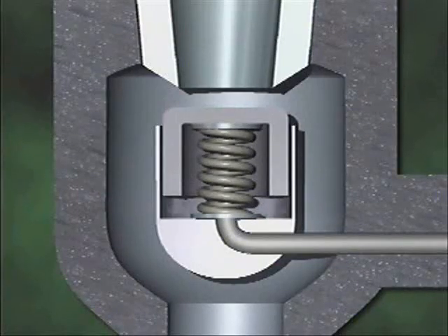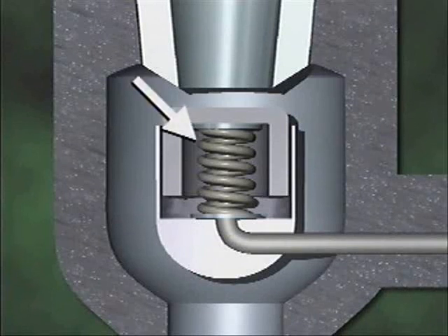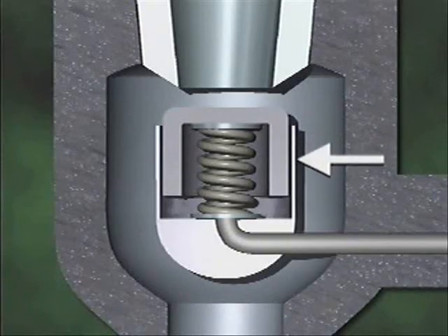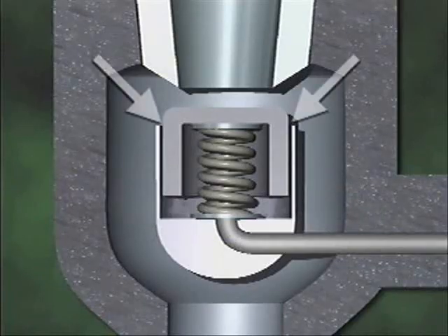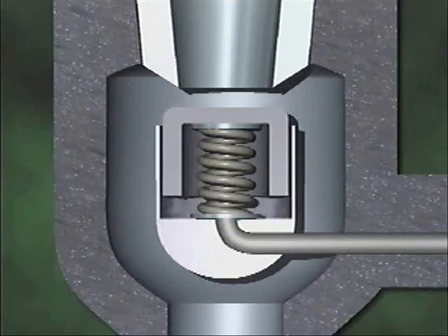The disc opens downward, allowing the steam to escape through the outlet at the upper part of the valve body. Also, in this example, the spring is placed below the disc. The valve also has a disc guide, which is a sleeve that aligns the disc with the seat. A small opening between the disc guide and the disc allows system fluid to pass through from the inlet to the bottom of the main disc.